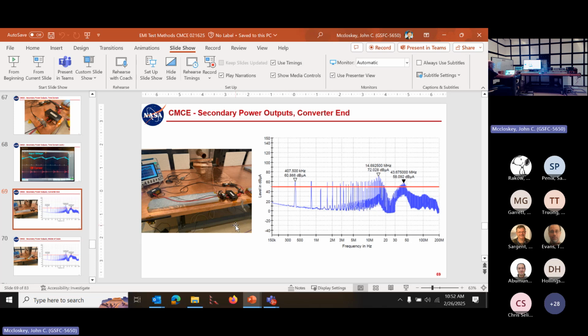And then we'll do the same thing. We know this is about the same length as the cable on the input side, so it's about 1 meter. So we should expect above about 30 megahertz, the cable is going to be electrically long, and then we should start seeing transmission line effects. So we'll move the current probe to the middle. And let's pay attention to what's happening up here.